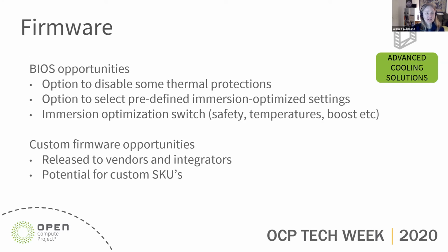If we're looking at the firmware for BIOS opportunities here, here's really the opportunities to be able to disable some of the thermal protections. So many systems have thermal sensors to determine what the environmental temperatures are, if it's safe for the IT equipment to operate or switch on. And some of those thermal limits can potentially be increased when dealing with immersion.